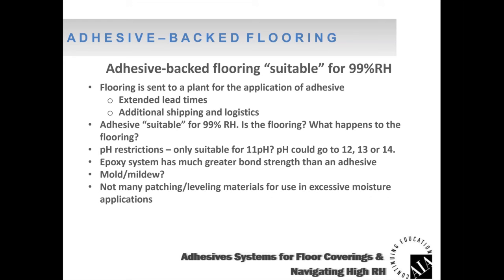This is a big one for me because it's misunderstood throughout our industry. You could have a floor covering and adhesive system that's a very high RH, maybe even 100% at that point, that can handle liquid water and extreme pH. Your typical patch or leveling products out there on the market are not suitable for that application. Pick a manufacturer, it doesn't matter to me. We all make the typical patch and leveling products, and they're all not suitable for liquid water for extended periods of time. Products have to be formulated to do so.